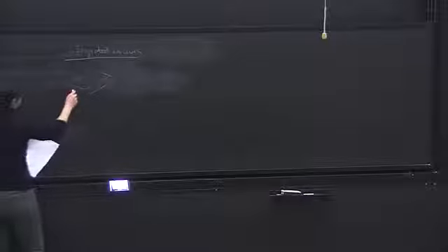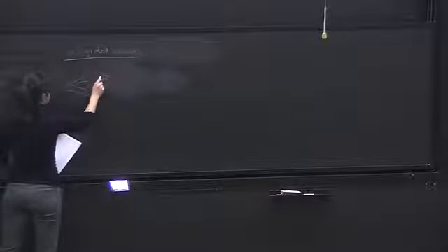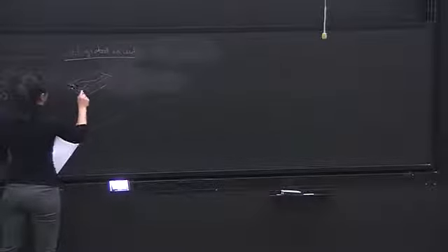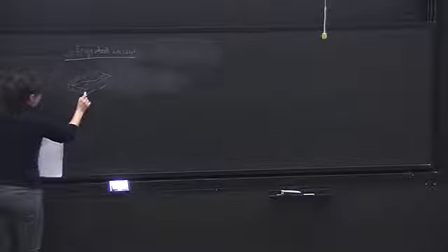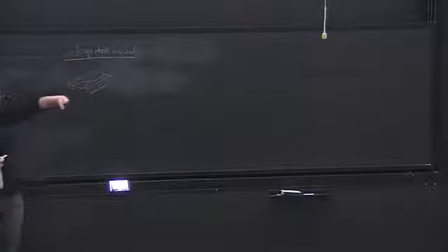And then in this little block, they write these waveguides, which look like that. The way they build them is they grow some silica, and then they grow something that corresponds to the waveguide out of a doped silica, and then again put some more silica on top of it.